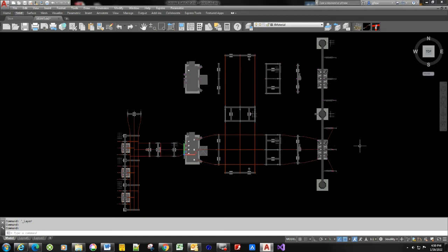We've got two bays with an incoming 161 kV line, comes through an isolating switch, a breaker, a circuit switcher, another isolating switch, a cross bus, support structure, a 161 to 12 kV, 30, 40, 50 MVA transformer, a 12 kV isolating switch, meter structure, a support structure with a station service transformer, and 3 outgoing overhead bays.